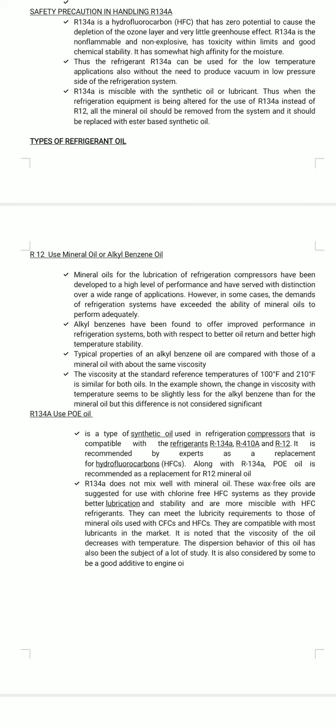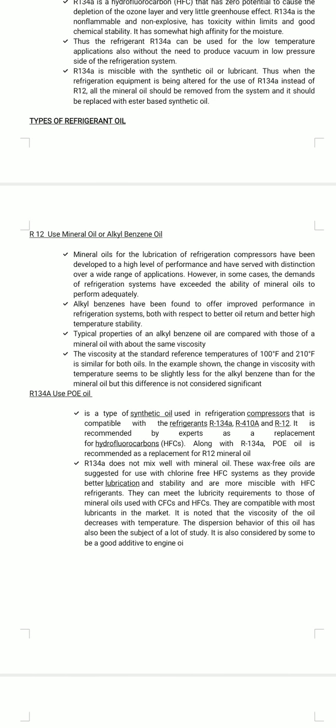Thus, the refrigerant R134A can be used for the low temperature application, also without the need to produce vacuum in low pressure side of the refrigeration system. R134A is miscible with the synthetic oil or lubricant.